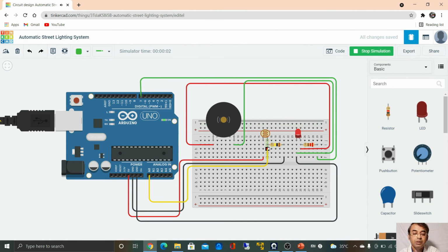Okay guys, as you can see, the buzzer is ringing and everything is on. So now click on that. I will increase the differential value. As you can see, when it is like this, that means it is off, that means sunrise. As you can see the symbol of sunrise. So when we shift this to the left, as you can see, it will be on, that is the street light will be on and the buzzer also starts ringing. On sunrise, that means the LED is off.